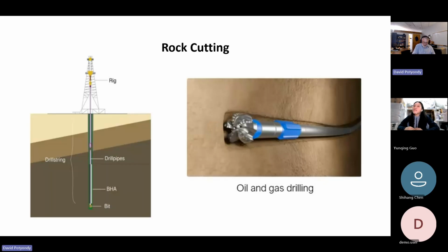And so there's two sorts of tests that you want to do. You want to be able to do a dry cutting test, and you would ideally also like to do a cutting test that actually has fluid with confining pressure on there. And those second kind of tests are very difficult to do in a laboratory. Nowadays they can actually do them, and they use mineral oil, which is a clear fluid, and you can actually see inside of it. So you can see the rock and the cutter, and you can see inside, and you could control all this.